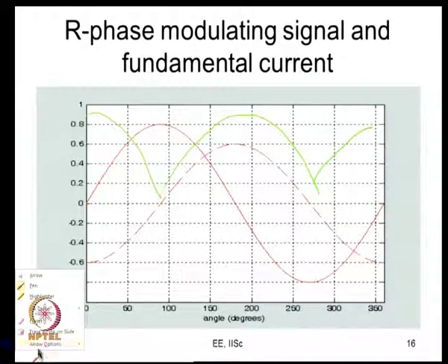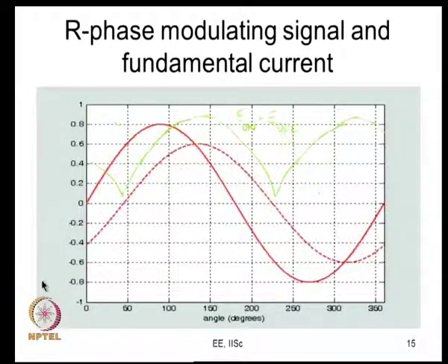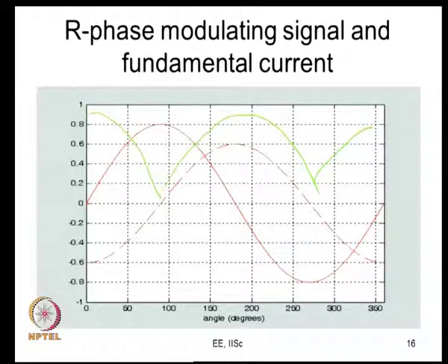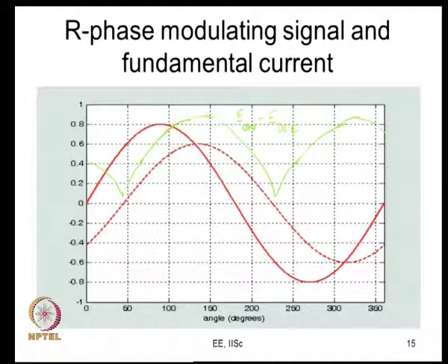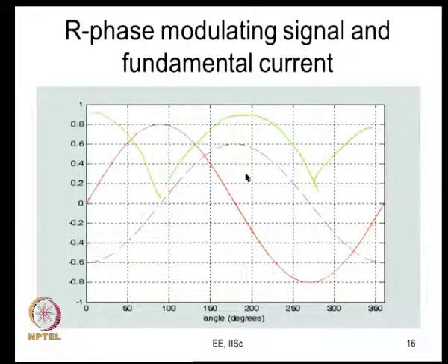So, if you look at the difference between here and the previous one, you look at this and that, there is no difference, there is a difference in phase, otherwise there is no difference. So, the variation of the switching energy loss is quite similar, and its average value will be equal. So, what does it mean? What is the difference between here and there? The load current is the same, but the power factor is different. So, even if the power factor changes, you can say that the switching loss does not change significantly.